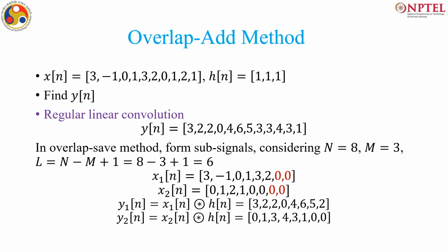Again, if it is confusing, let us take an example. Let us take the very same example. So, this is my signal and this is the result of linear convolution, and we have all this chalked out easily. But here what we are doing is, we are taking 6. So, 6, 1, 2, 3, 4, 5, 6, and the remaining will be this. Of course, since there are zeros after this, I have taken 0, 0, and these m minus 1 zeros are padded at the end.